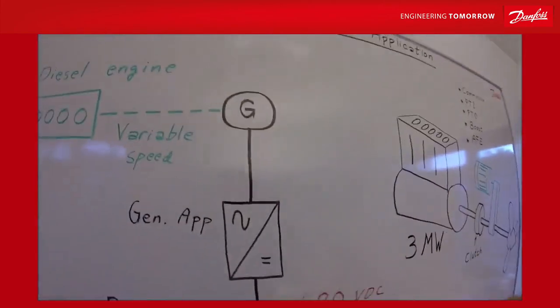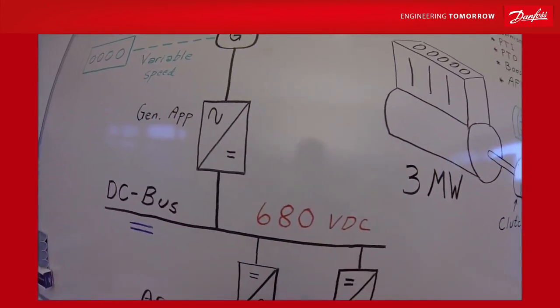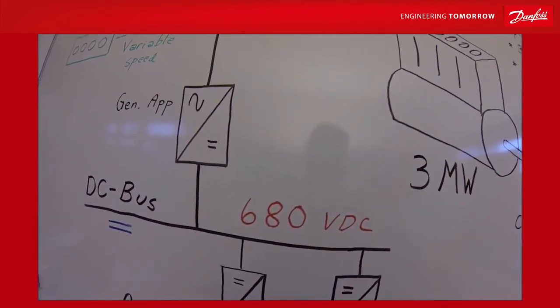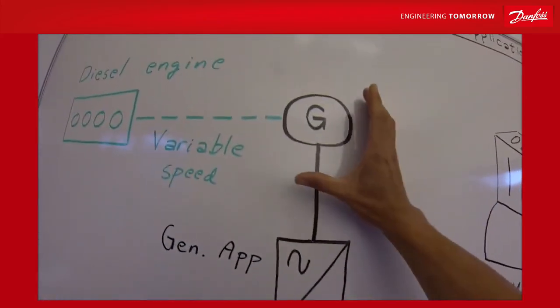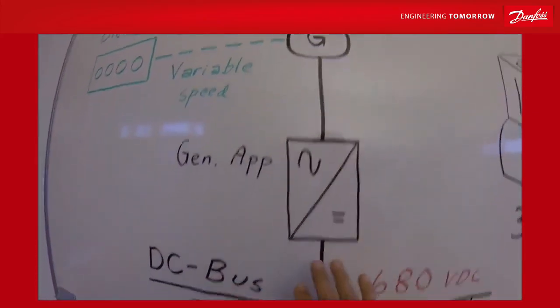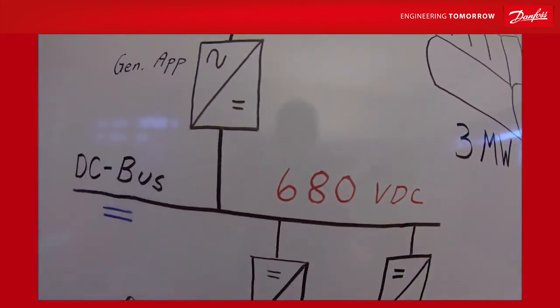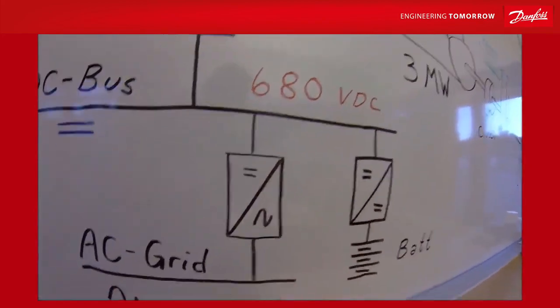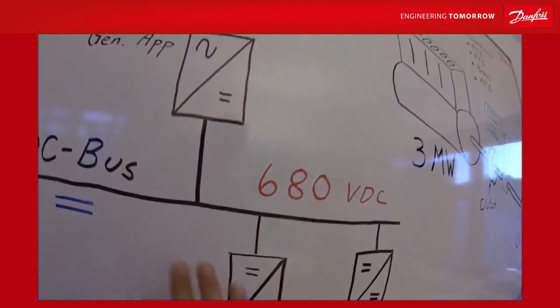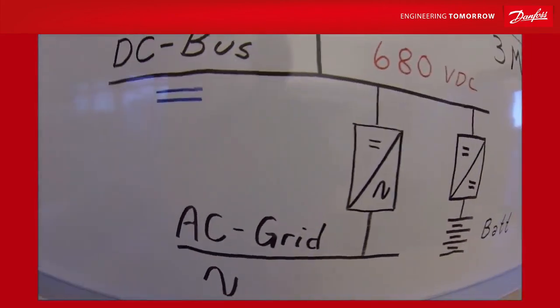Say that when it works in PTO mode, it only aims to produce a constant DC voltage of your selection. It will then extract energy from a motor or a generator by braking on it and put it into the DC bus, aim for the constant DC voltage, and any consumers on the same bus system can extract current and put it into batteries, AC grids or whatever.